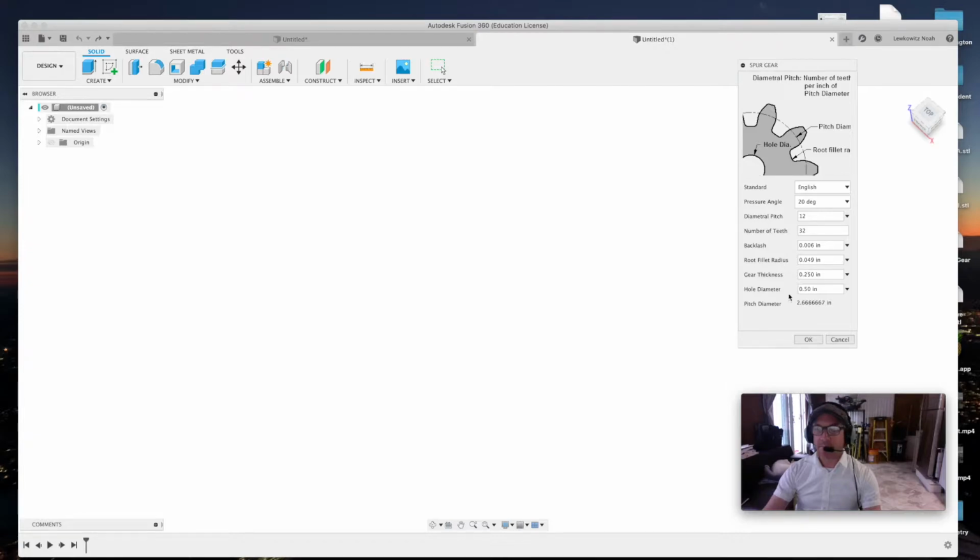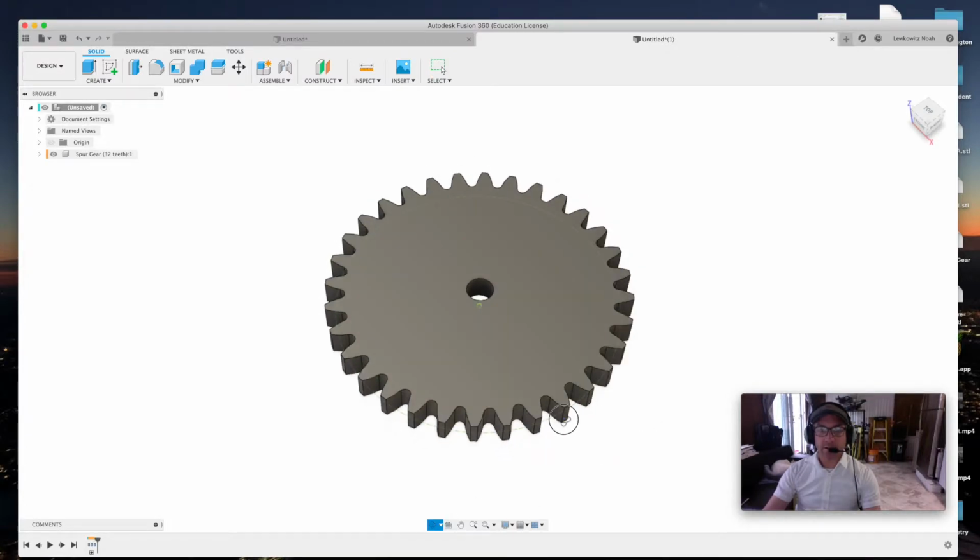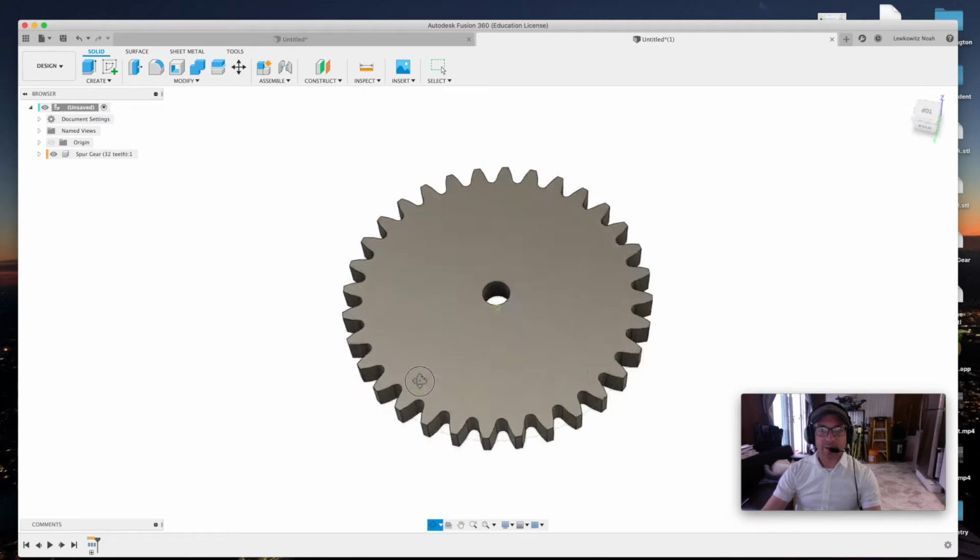However, today we're not going to do that. We're just going to keep it at 1/2 inch. All right. Actually, let's do 0.25 inches. So here's the settings you should have before you click OK. And look at that. We got ourselves a gear. Not too shabby, huh?